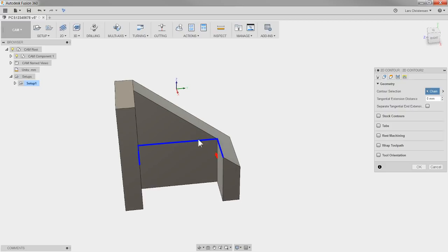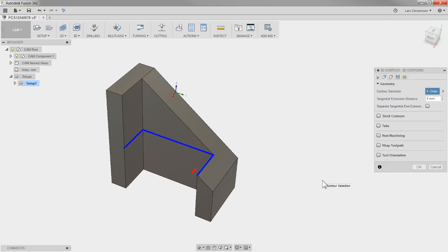It will machine to that height. So this is how you can select. Sometimes you have an opening, but there are some radiuses on the bottom, and you have a weird development. This is how you can do that. Select the chain, reselect it again, and then you can go in and select that open contour, selecting the edges that you want.